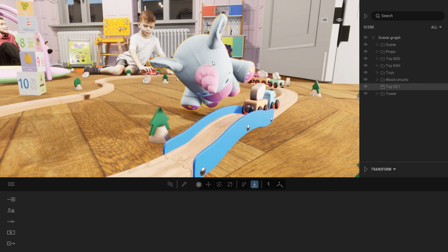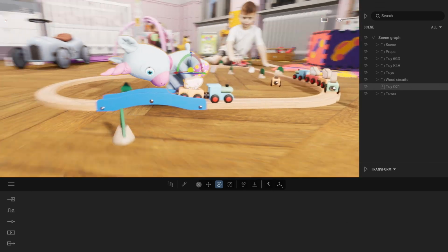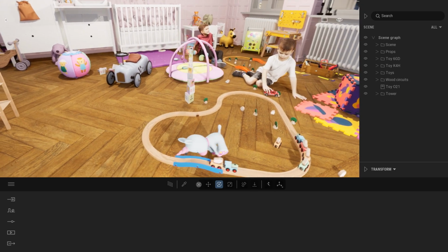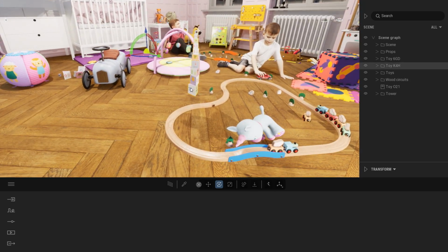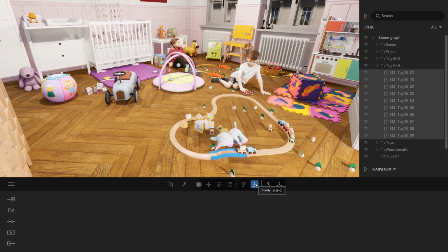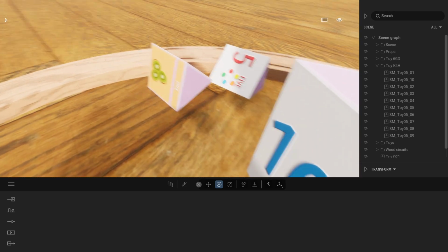If you want to have something a bit more precise, once you activated the collision, you can just move it a bit manually. It also heavily depends on the geometry you are using. So for example here, let's select that pile of objects. I will do the same thing, move it up in the air and press the physics to make them fall. And since they are a really simple geometry, the physics applied onto them will be much more accurate.